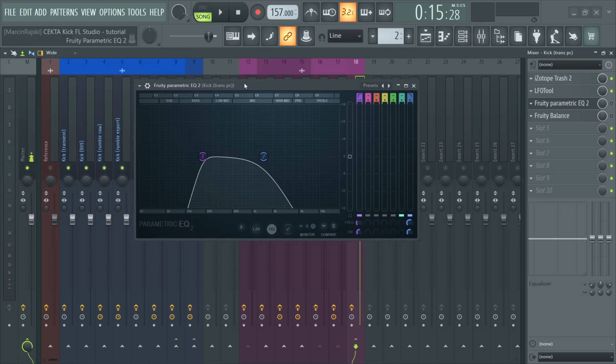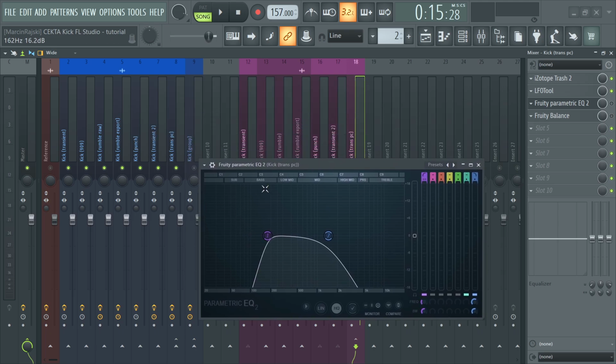In the equalization, again, I'm using a high pass and a low pass filter at the same time. A high pass filter is added so we don't mix the low frequencies. And because the amount of crackle and noise is a bit too high, I need to use a low pass filter to make the transient sound dull again.